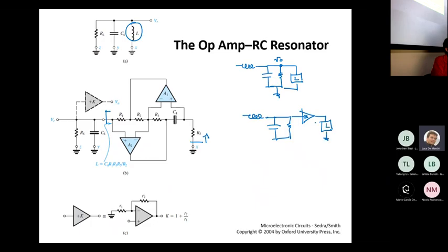In this way, the buffer is typically characterized by a very high input impedance. Ideally, this input impedance is infinite, so it has no effect on the inner node of the LCR resonator. So that's the reason why you see this buffer here. You are not plugging V out directly to this node, but you are inserting a buffer in between.